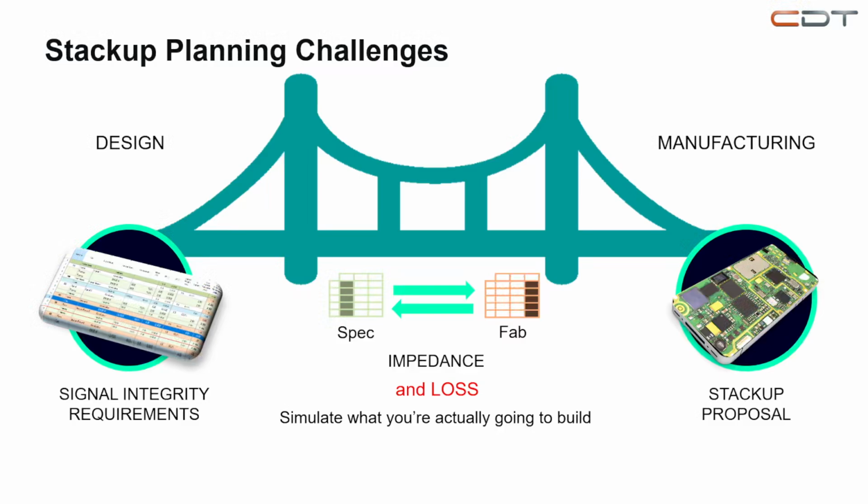ZPlanner Enterprise eliminates this complexity and seamlessly links your design, your signal integrity requirements, and your OEM specifications directly to the manufacturing process. This means your stackup proposal matches your design intent, and you simulate the real-world build, and your planned impedance and material choices are precisely what the fabricator delivers. In short, ZPlanner automates coordination across design and fabrication, giving you confidence that your PCB will meet performance targets without additional iterations or problems.